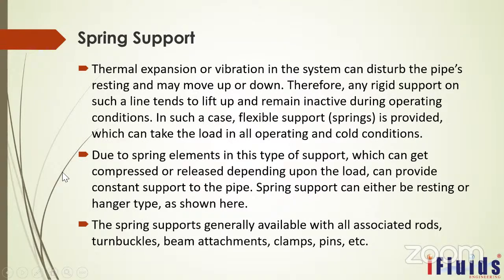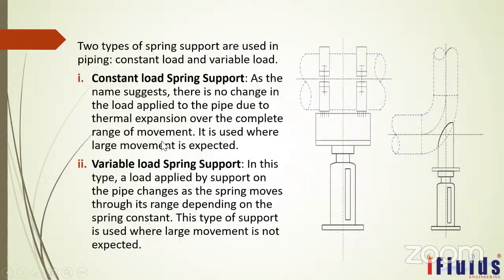And another special type is the spring support. This kind of support is preferably used where the thermal expansion and vibration expectation is very high, like a sudden expansion that can happen at any time, or if we are expecting turbulent flow in that pipeline. Those kinds of areas need this kind of spring support. Wherever the guide support and the shoe support we cannot use, in those areas we have to use this spring support. I will explain here.